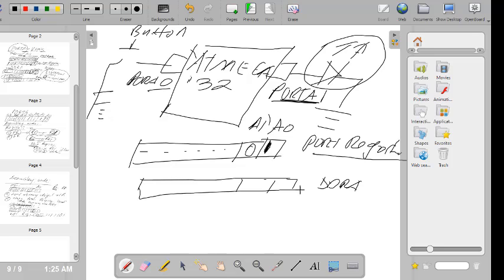So when it comes to the data direction now, we need to think. If this is A0 and we are meant to configure it as an input port, then definitely the DDRA0 of it, and this is the DDRA1 of it. So the DDRA0, which is this port right here, would definitely benefit from being an input port because really we are connecting a button.